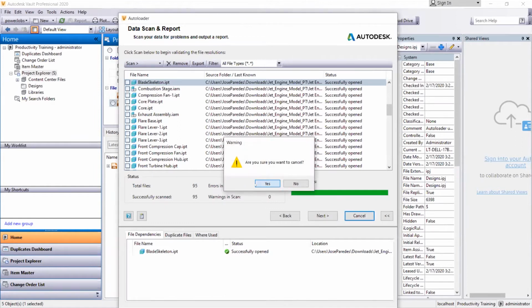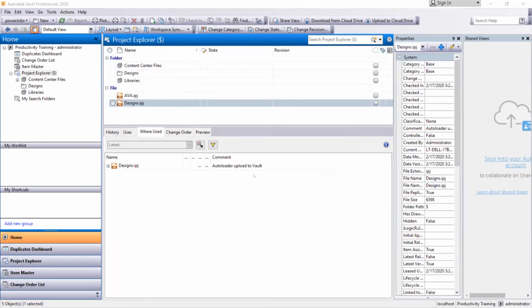But again, you don't want to go ahead and just start removing sub-assemblies or assemblies. In this case, it worked out really nice because it wasn't related to the top level assembly. So it wasn't going to cause any issues. But in most cases, if it is a sub-assembly, it'll affect an assembly above it. And that might be a sub-assembly as well. So it'll start this chain of assemblies being affected, and you might end up removing more than you intended.